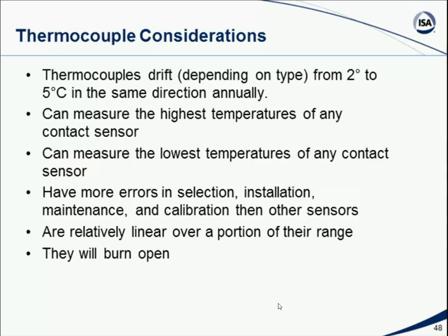The other thing about thermocouples is they are, as I said, just a couple of pieces of metal, sort of stamped or spot welded together. Thermocouples have a couple of failure modes. Quite often, when they're used at high temperatures, they'll burn out. They'll literally just burn open circuit. Fortunately, most systems have the ability to make that determination. The other problem you run into sometimes with thermocouples is they will be crushed, and they will actually short out.